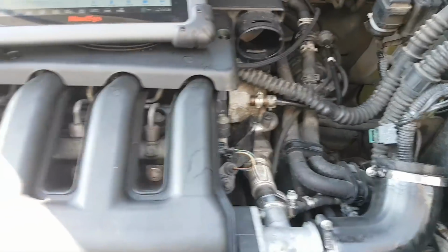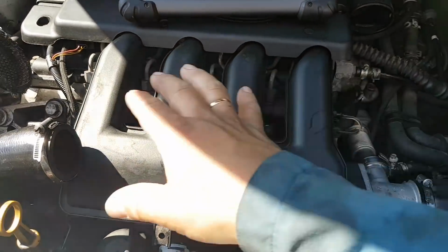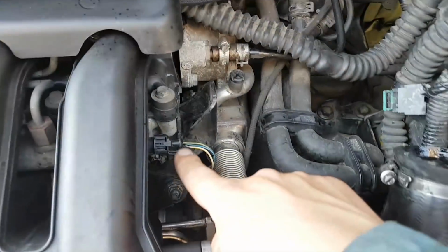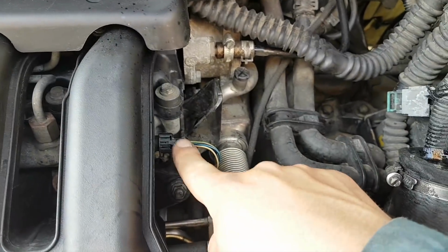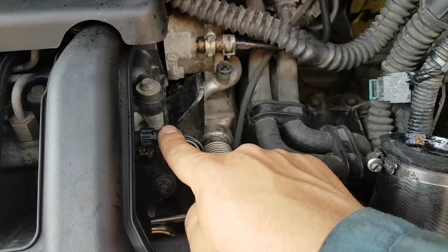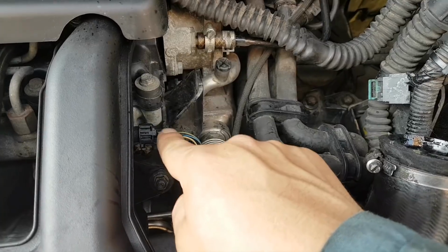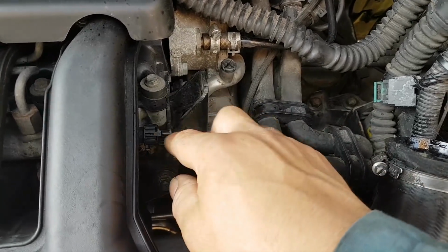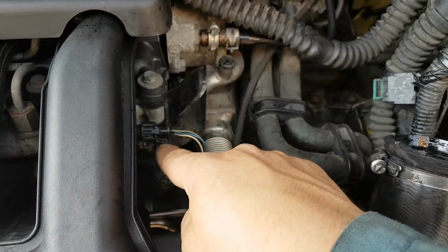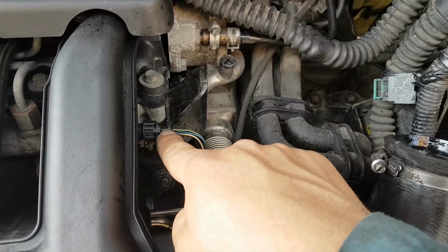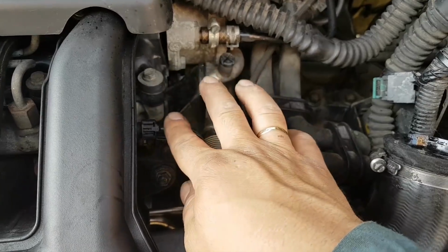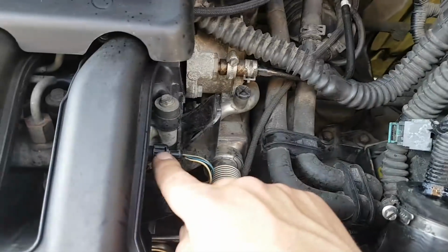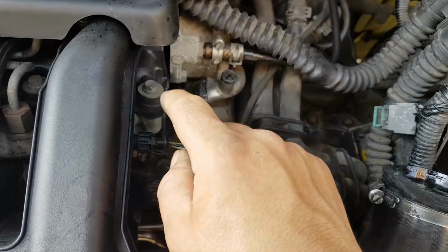So what have we done so far? So I took this sort of intake here. I know this is the common rail fuel pressure, but was one thing that I didn't like when I unplugged it, which was full of dust. The plug, I should have recorded that. The plug was full of dust. The pins were a little bit too opened. I don't think that was causing any problems, but we repaired that. I compressed the plates, cleaned it properly with some electrical cleaner. Looks much better now.